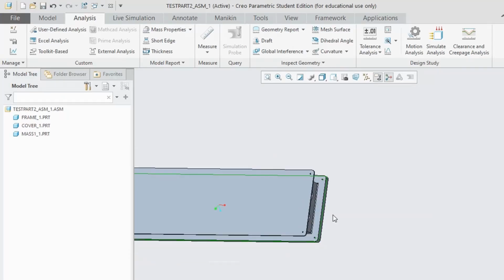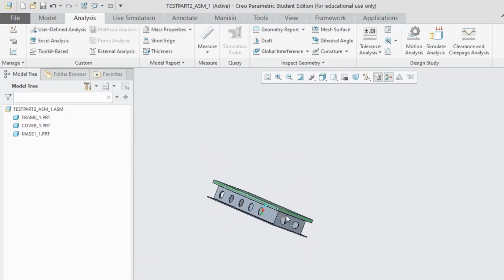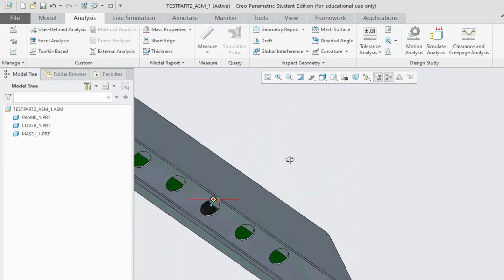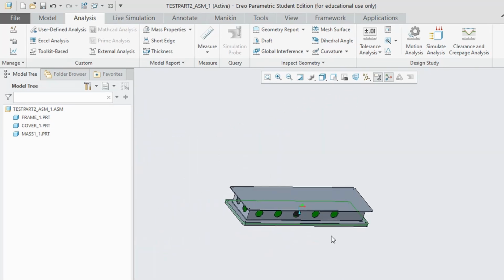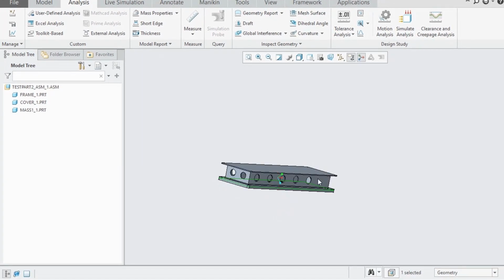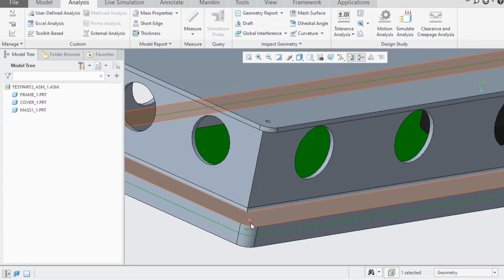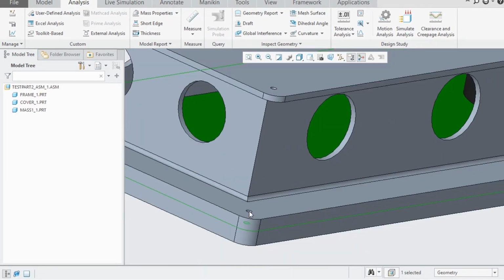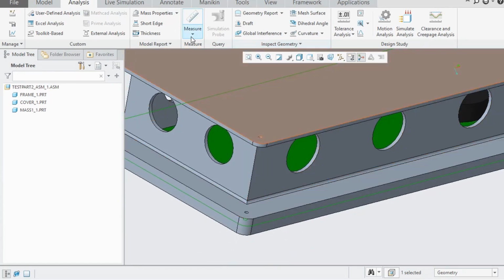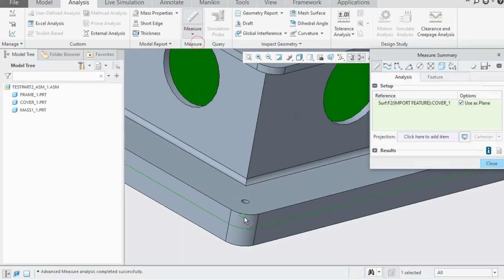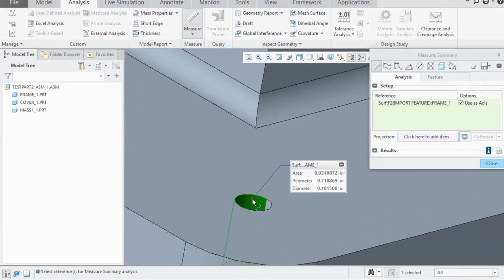So this is my geometric model of that component, and you can see here if I orient it correctly, this thing is symmetric, and element 3 would be this hole right here. So what am I going to need for my calculator? Well, let's go ahead and measure it. I'm going to need the clearance hole diameter. My clearance hole diameter is 0.1015.